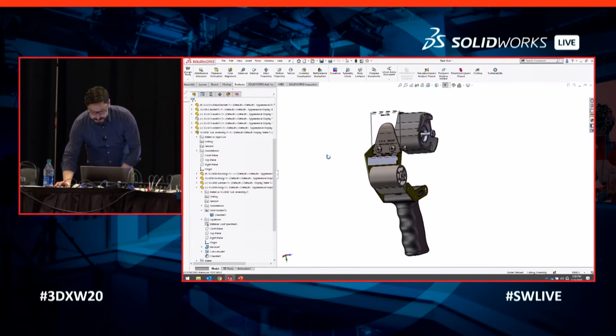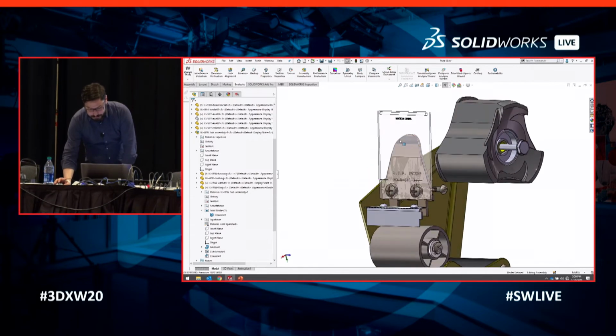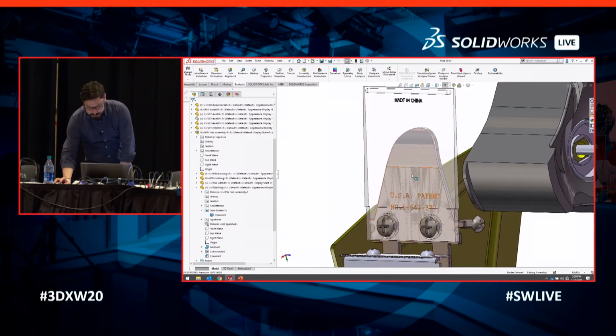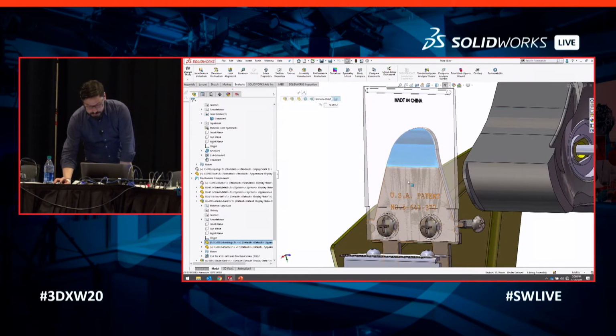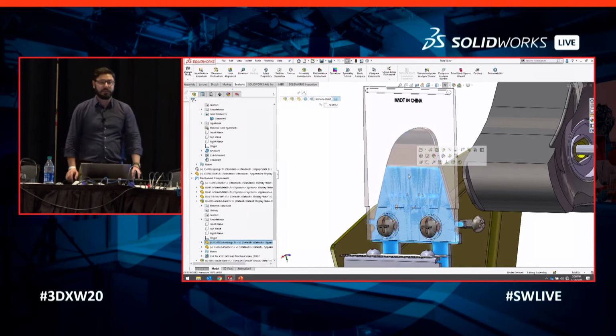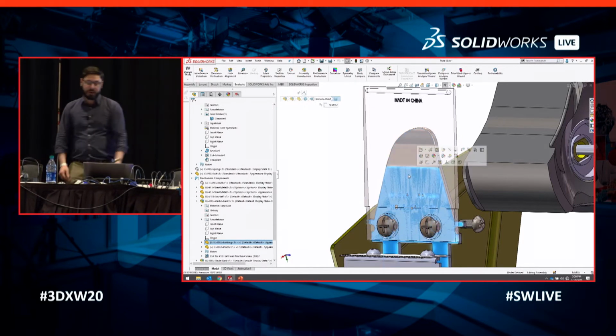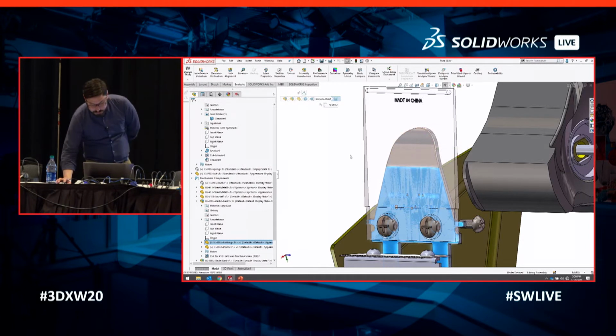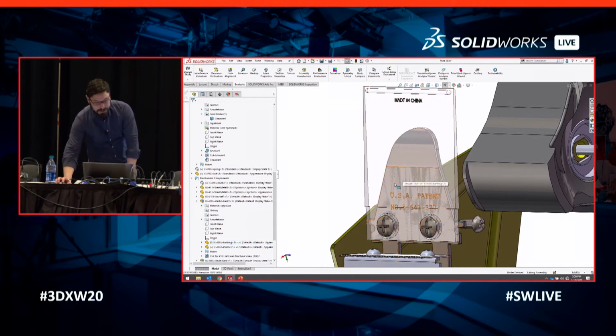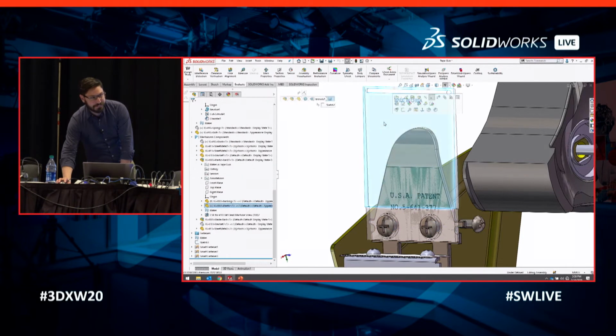So if you've got a transparent part, by default, SOLIDWORKS is going to automatically select through that transparent part to whatever your part behind it is, okay? But if I wanted to grab this glass shield here, I mean, everybody's trick is, let's go move the mouse a little bit and then we'll click over here, right?